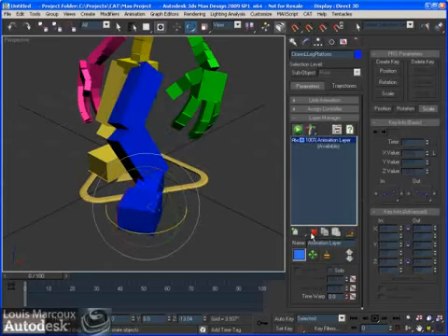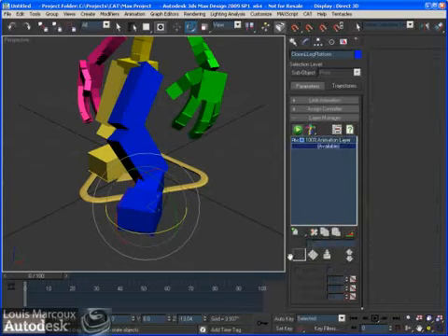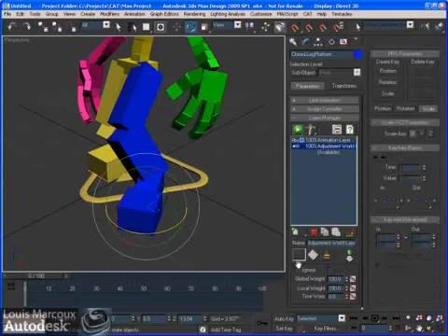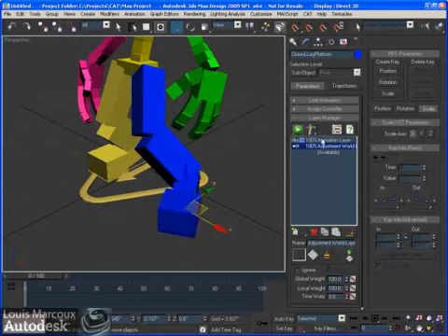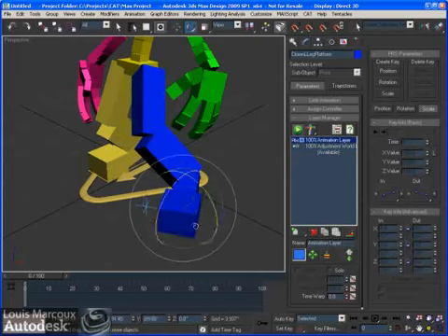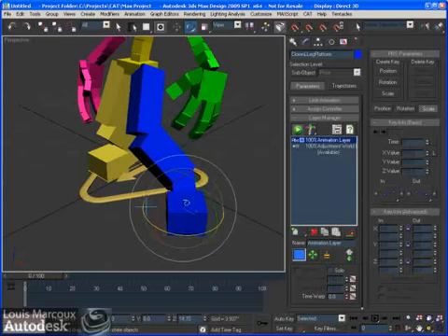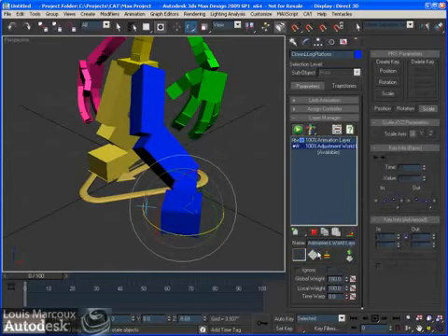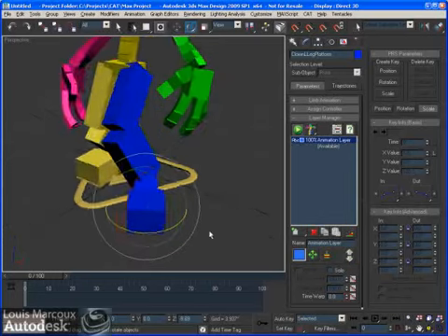So I'm going to trash that again and do it in world space. So if I go here and say adjustment world, and I move it to the side like I did before. Now if I grab this animation layer and I rotate it, you'll see that it's rotating around this local pivot point here. So that's the difference between the two. Hopefully you get that difference.